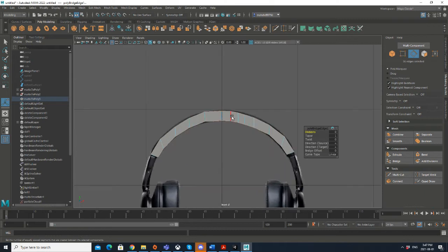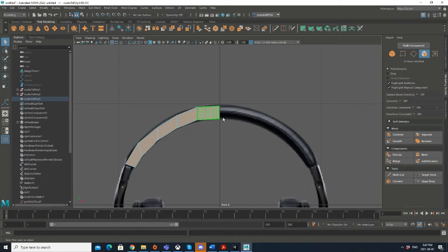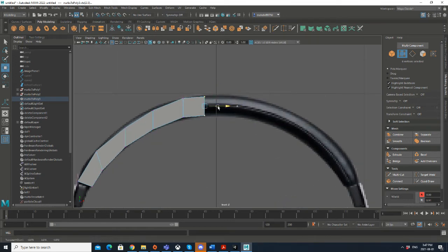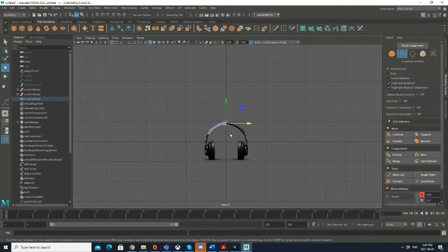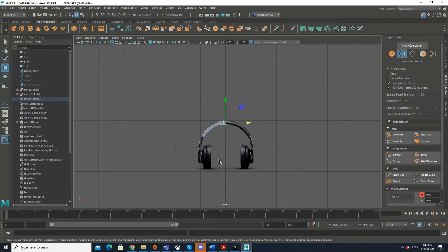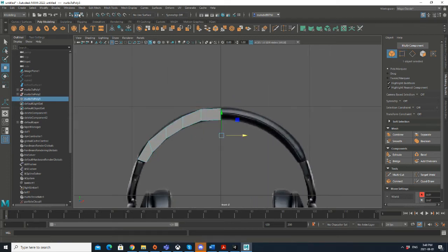Yeah, okay, great. And as I said, you could go with only having the left half of your model from the beginning, or if the model structure is not as you wished, you can always delete the right side, and make sure that you put your vertices exactly on this line by holding X and moving it. It just snaps your vertices into the green lines. Then go over your objects,